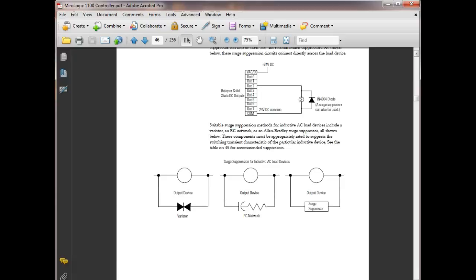So we have several types. This is something that we haven't gone over very much, and this is noise suppression. So on the AC load, we would use the Varistor. This is another network, a surge suppressor. If we're using any type of solenoid or relay coil on a DC module, we need to put what we call a flyback or counter EMF diode on there. So if you were over there looking at the Siemens PLC, every contact that controls a solenoid would have this diode across it. I don't know if I've got stuff over here to demonstrate what these coils will put out when you turn them off. What happens is that when you turn them off, all that magnetic field comes collapsing back into that coil and produces an extremely high voltage. When you take AC, we'll use a neon.